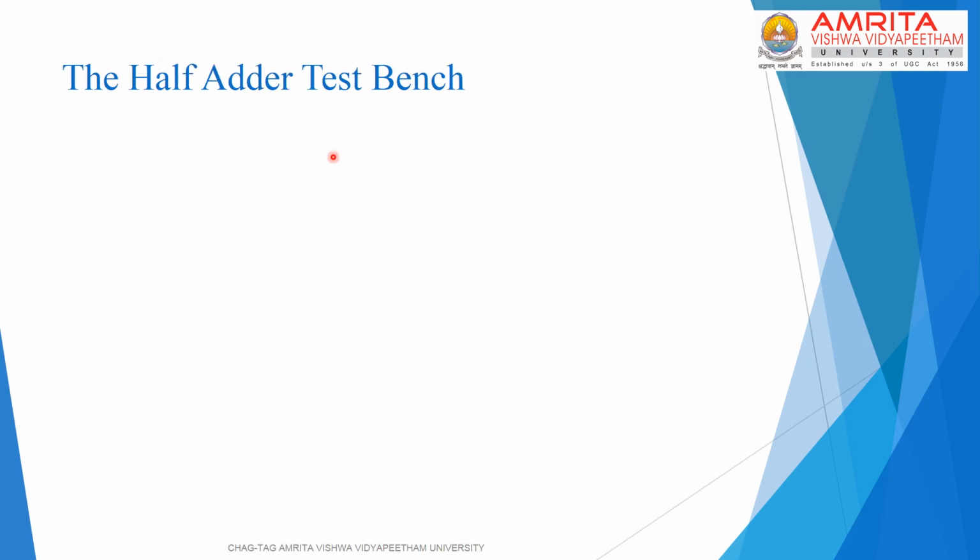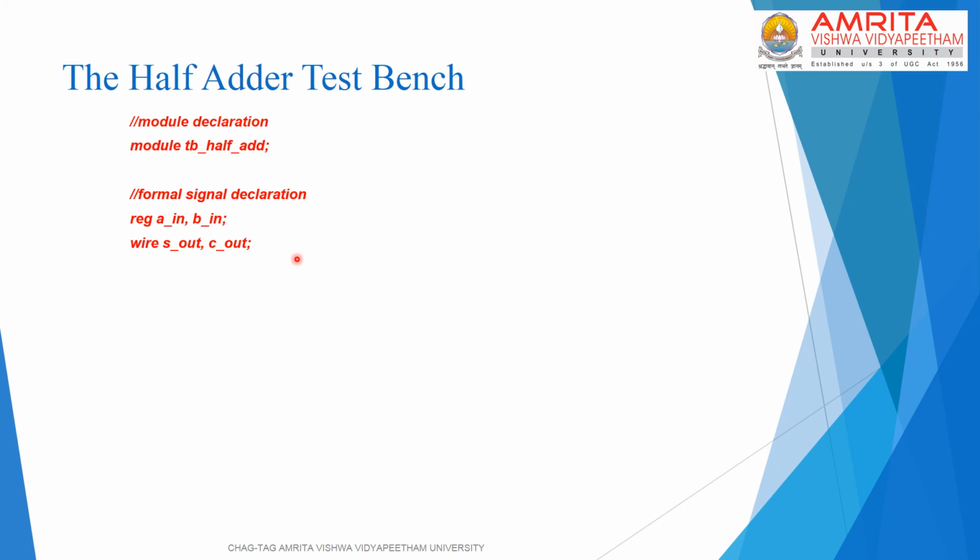The test bench is a portless entity. In the declarative part of the test bench, the signals which are going to be mapped onto the input and output ports of the device under test are declared. So there are two signals A in and B in which are declared to be of type reg. These signals will be mapped onto the input ports of the device under test. There are two signals S out and C out which have been declared to be of wire signal type.